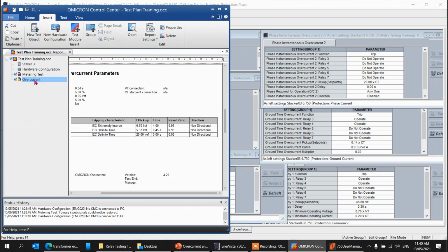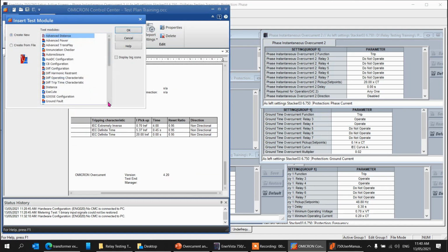Okay, pick up. Normally, I think this overcurrent, I will change the name to overcurrent pick up and instantaneous, because it's a combination of the two. So we do pick up, add another module, and since we do pick up, it depends. You can do quick CMC as well, and do that on the curve one. But that one is quick. We've done the quick CMC.